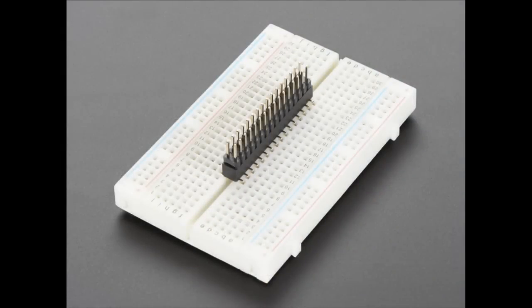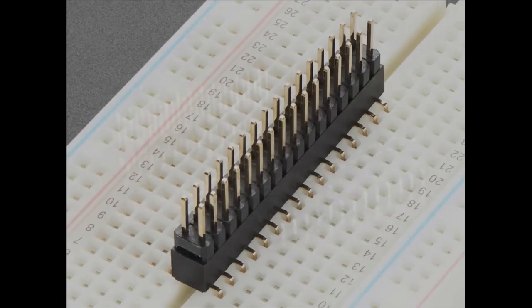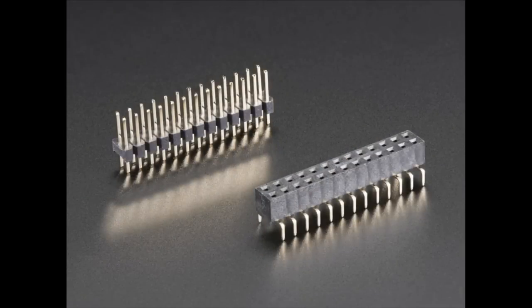These are weird. These are what I call IDC Breadboard Friends because they have no formal title. And this is basically the thing that you're like, wow, that's so handy, because I have these IDC cables because it's such a common cabling system used in electronics. And you want a breadboard with it, and there's no way to do that because the IDC cable does not, there's a gap in the middle of the breadboard. So this is 2 parts. On the right, you see there's a sockety part with the legs that come out like a little centipede. And then there's a male header that plugs into it.